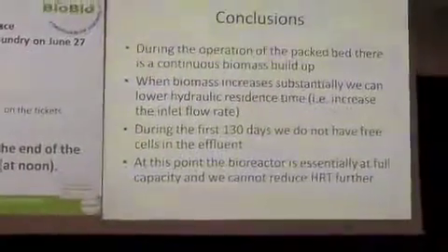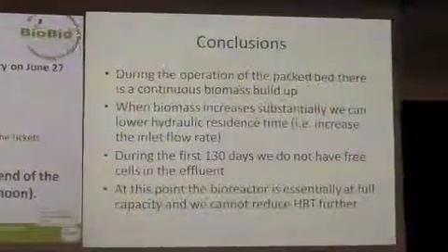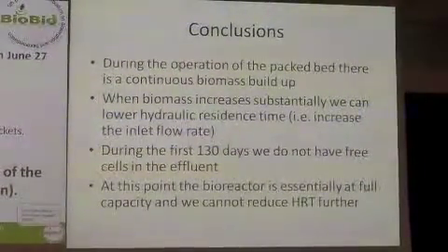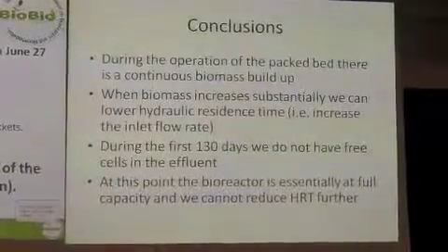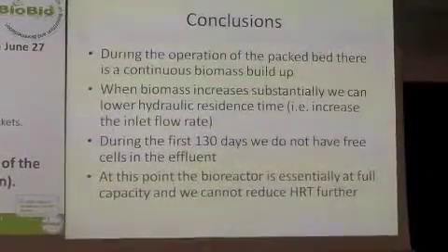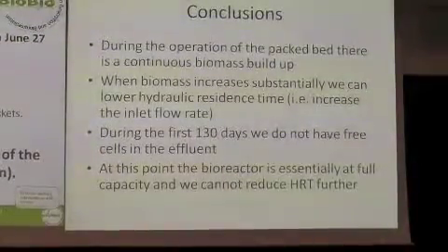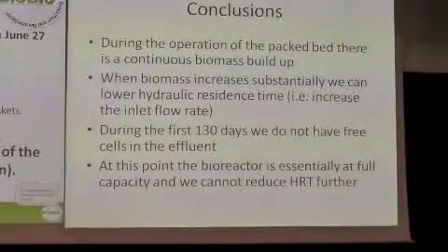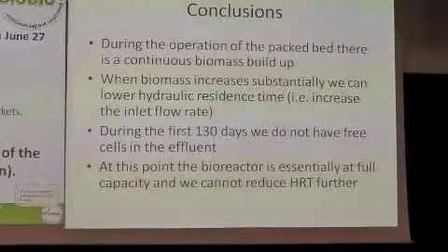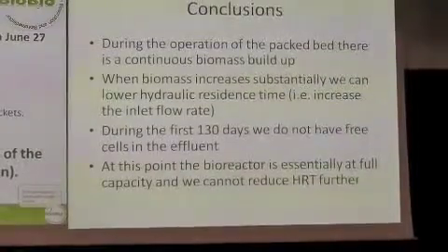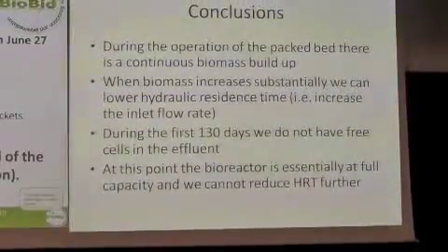So as conclusions, during the operation of packed-bed bioreactors there is a continuous biomass build-up, and when biomass increases substantially, we can lower the hydraulic residence time, increasing the inlet flow rate. During the first 130 days, we do not have any cells in the effluent, and at this point, the bioreactor is essentially at full capacity, and we cannot reduce HRT further.